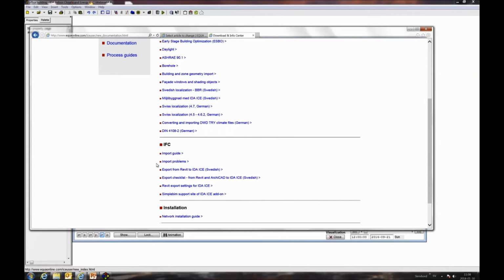We have a new question. With the new daylight model, is it possible to calculate different reflections from outside areas, like reflectant buildings or reflectant roofs? Yes, in the daylight calculation with Radiance, you do take into account all surfaces on the outside with reflections and all properties that you can set. But you do need to set the correct properties on all surfaces, of course.